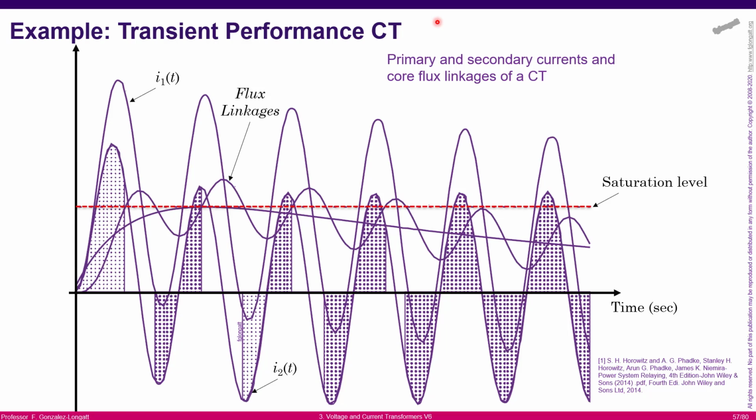Okay, during transient processes, the saturation of the CT can be extremely important, and all these phenomena must be examined carefully using time domain simulation software. In this course we are not going to do that, but the idea of this example is that you realize that the transient performance of the current transformer is a bit complicated. Of course, modern simulation software have the capability to do so.